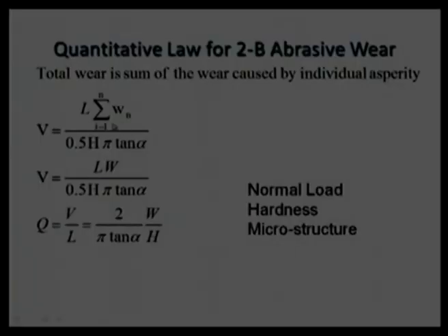What we need to do is summation. So, asperities 1 to n, and load may be different in every case. So, summation will turn out to be overall load, overall normal load which is applied. Distance can be easily calculated, it can be easily measured, and tan alpha we do not know, that is a statistical parameter. For few asperities it will be maybe 10 degree, maybe few asperities it will be 80 degree, few asperities it will be 50 degree. So, still we are assuming there is a statistical parameter, we are not taking any decision.